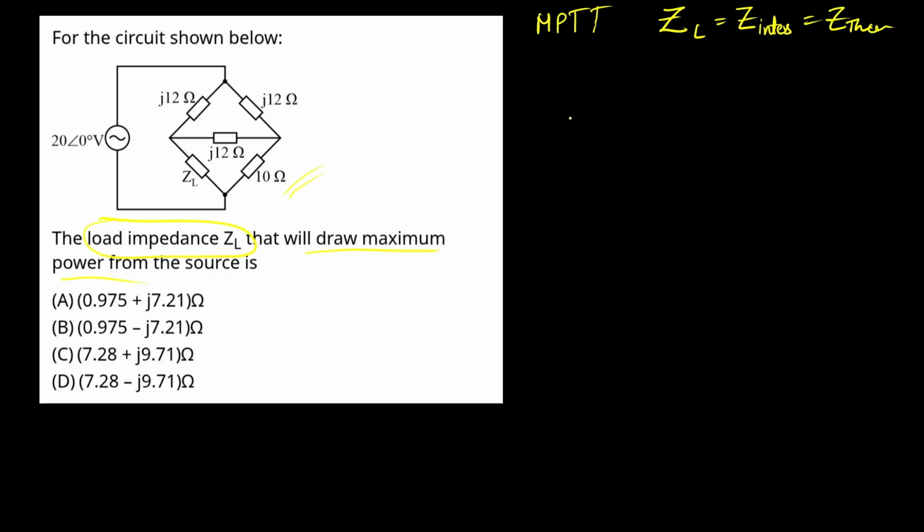So to find the Thevenin's equivalent, you can short circuit the voltage sources and open circuit the current sources and look at the equivalent resistance from the load terminals. So that is Thevenin's equivalent. But you can see it is difficult, because here it is delta connected, these three, and all are equal in magnitude. So simply we have to convert from delta to star. So it will be divided by 3. So we will get an equivalent circuit something like this: